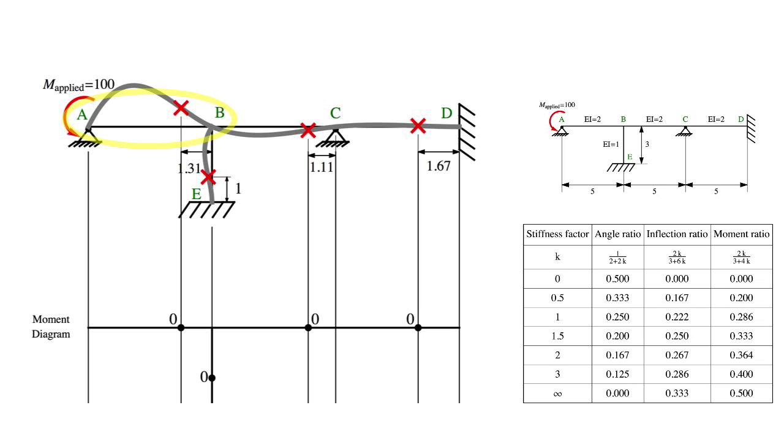It has an applied moment at joint A and there are no other attached members. This means that the moment will all be taken by beam AB at joint A, and looking at the negative curvature in the deformed figure near A, we then have a negative moment equal to the applied moment. We mark it on the figure. At end B of member AB, we have a transmitted moment.